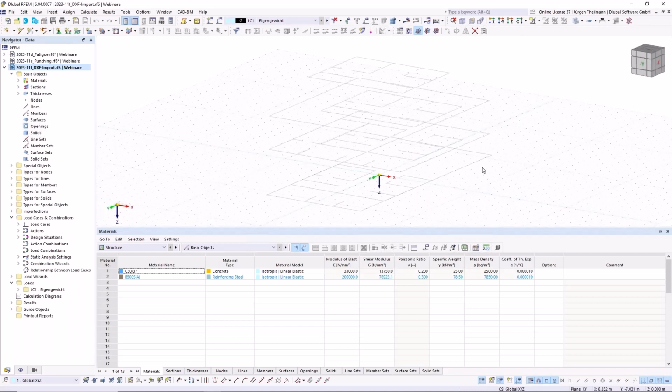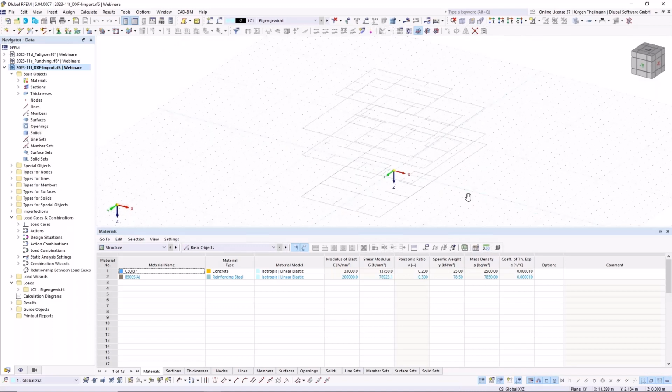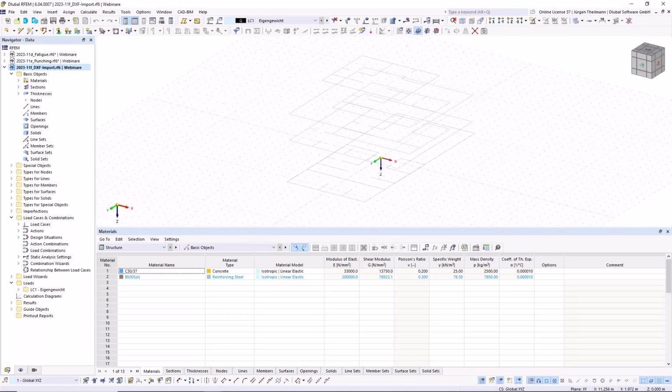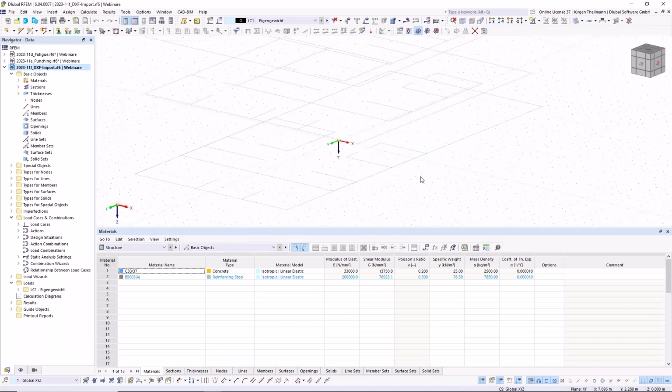How can I align my stories correctly? And here I have a small multi-story building. So I have 4 background layers inserted here. And what I intended was to have this wall, when you follow my mouse pointer, be on top of each other in all stories of my building.